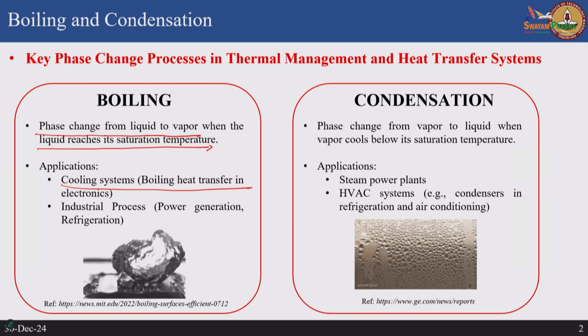conventional heat transfer modes? So, you have all the single phase heat transfer modes that Professor Marco covered, including conduction and single phase convection and radiation, but there is something very special about boiling or any phase change heat transfer, because the heat transfer coefficients are at least 2 or 3 orders of magnitude higher than your normal single phase convective process.